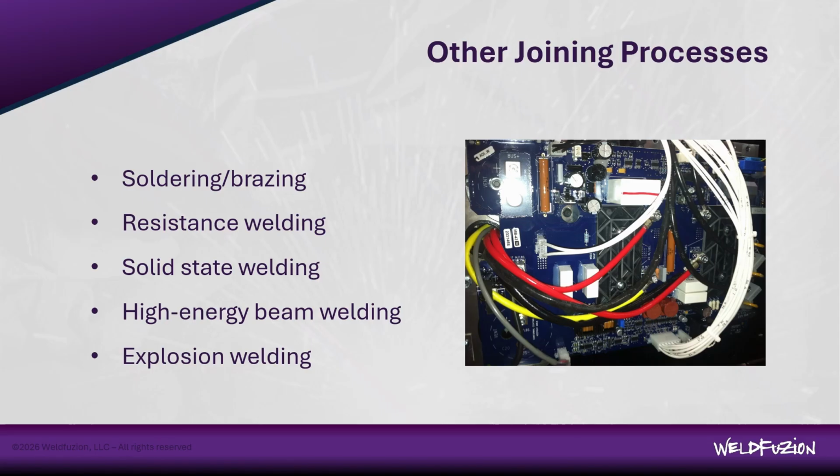All right. So, these are just a few of the many options that exist if traditional welding doesn't work. My advice is we keep it simple if we can. If we're doing things in industry, right, we can look up some references there. We can check how things are commonly done. We can follow our guides. And only go down the path of choosing an advanced welding process if other processes don't work, because they're going to be more economical. It's going to be easier to find employees that know how to do those processes.